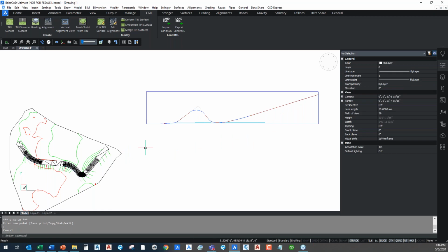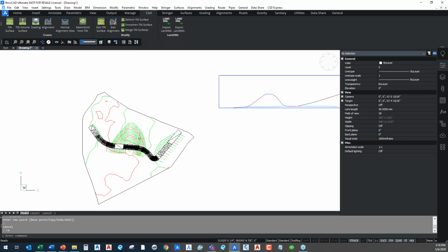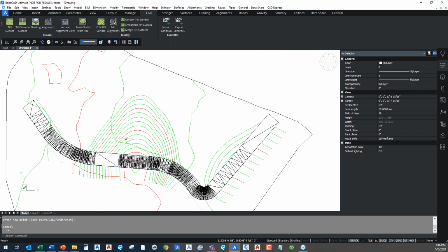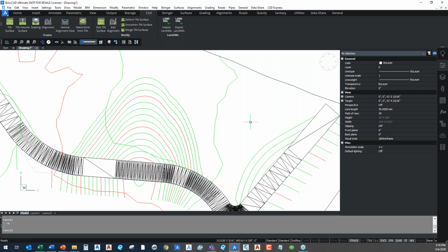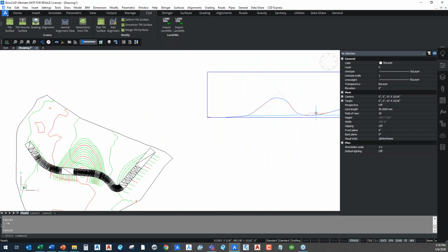And then after I go in and I just regen, you see the changes where I made the change to the slope, how it extended out the road, right? Made my road much longer from here all the way out to here, okay? You can see that just in seconds, I can easily modify using the profile view exactly what's going on with my 3D surface. So it's a very, very easy tool to use.